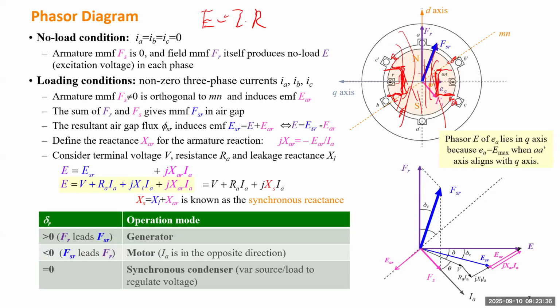So if you have a higher resistance, the current will be smaller. So the analogy in the magnetic field is the magnetomotive force, which is similar to electric voltage, and it is equal to flux multiplied by also R. The R usually we write with subscript M to distinguish it from electric R. We call the Rm the reluctance.